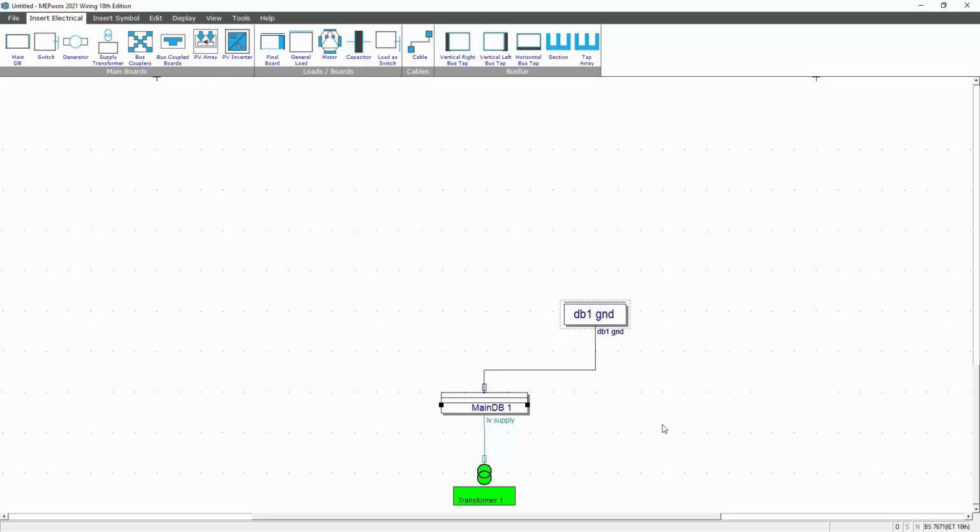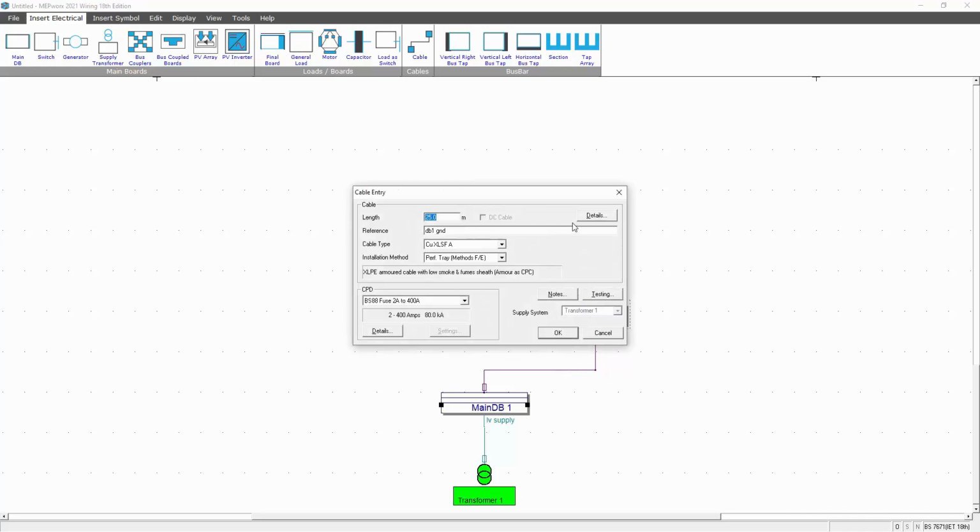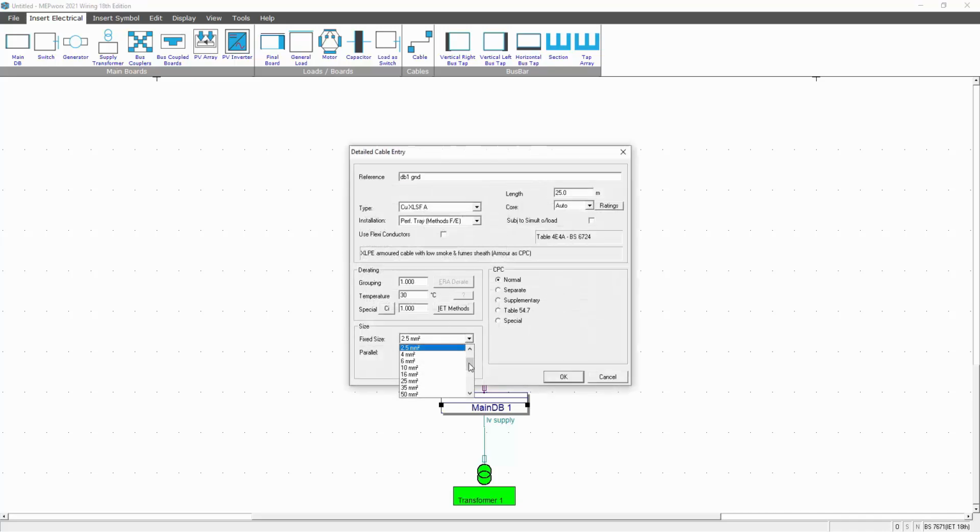So if you start fixing cables and you get problems with the cables themselves, it's probably because you fixed them and restricted for the given load or length of voltage drop. So that cable will then go red. Obviously we have no problems on this circuit at the moment, but when problems arise, the board or the cable will go bright red. You can access that and then you can solve the problem. I'm sure as we build this project up during these videos, we will get some problems, and I can cross that bridge when we come to it, and I'll show you how to solve various problems. So this is really about just adding the boards and setting up the system. So we'll unfix that cable, into the details, unfixed.